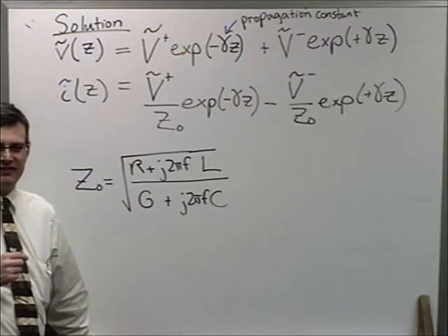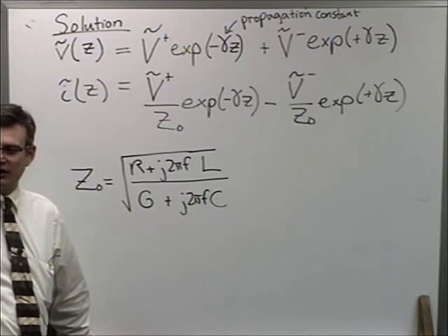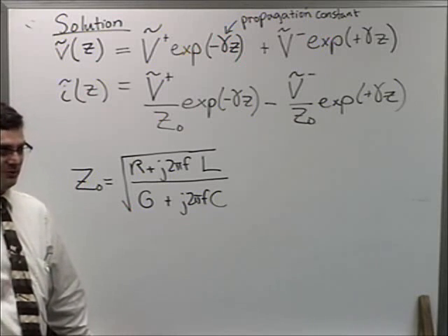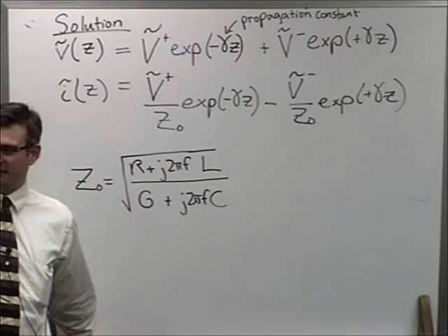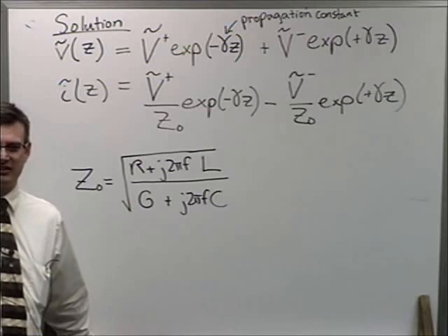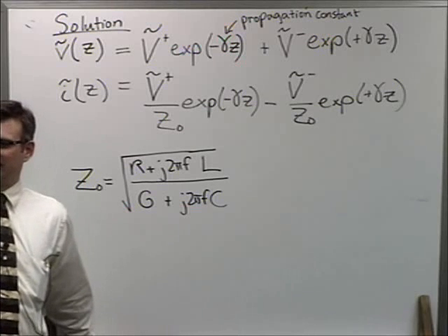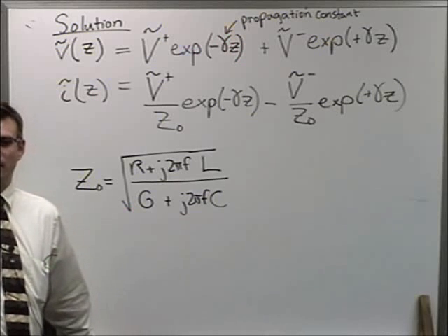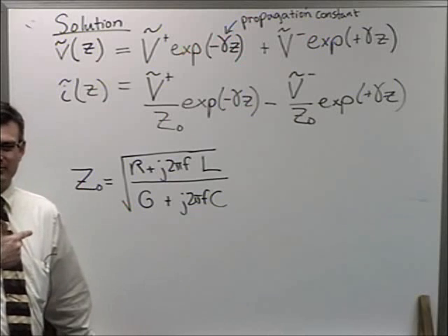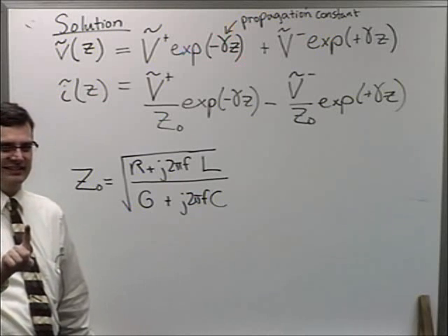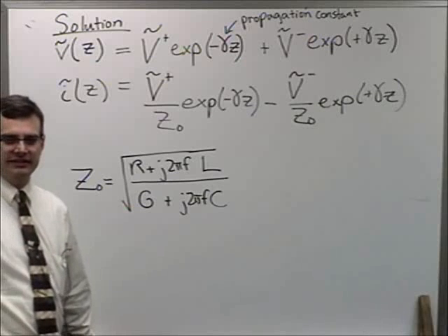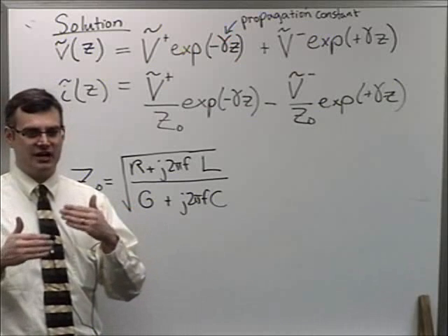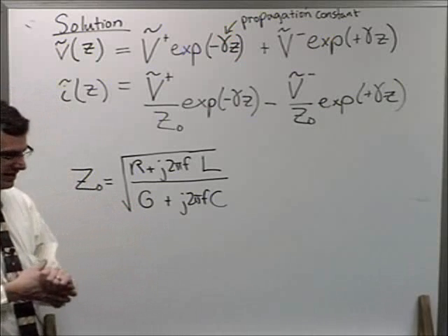And I say that's ironic because if you think about it, like if you're talking about a load that you learn in circuit class, when it was purely real, it was a purely resistive component and it was absorbing power, and it had an imaginary part. That imaginary part was like an inductor or a capacitor that was only storing power. And so there wasn't any lost power. But here it's kind of the opposite, right? Z0 real, pure lossless line. Z0 is complex, that's the sign that this is a lossy line. And indirectly it implies that it is a lossy line. Predominantly it implies that voltage and current are not carried with the exact same phase as they are on a lossless line.